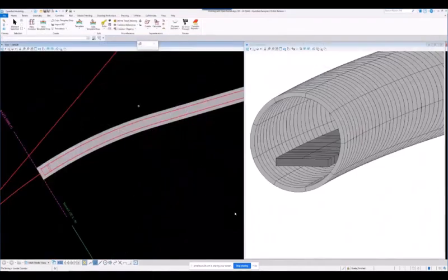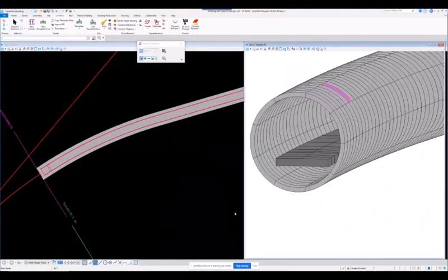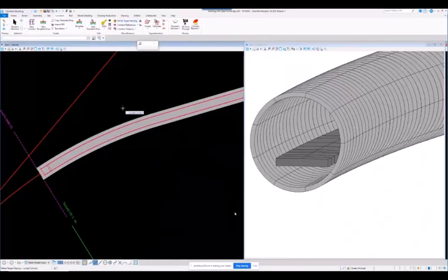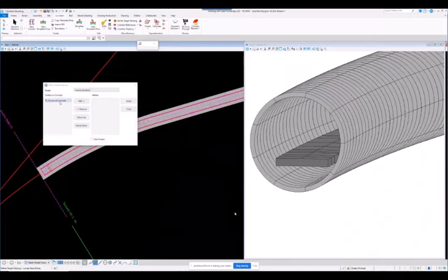How many people do TBM work? Well, we have a little example here. They have some fun here. But I think it's going to point out a few things here. I just have a corridor. I have a TBM. Basically, they're solids and stuff. So I already took these solids and I converted these to mesh. I did a mesh combined and I referenced it to the corridor. Well, if that's the case, I could go target aliasing, right? Pick that structural concrete, apply it. My end conditions and stuff can simply hit that mesh.